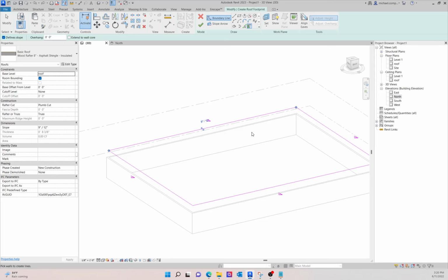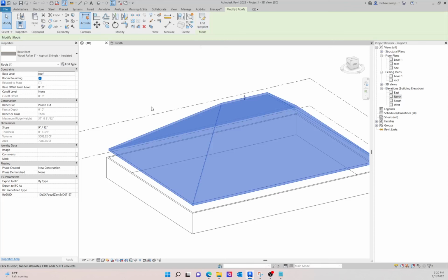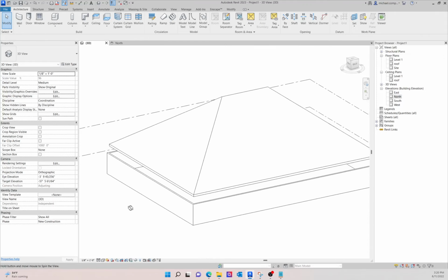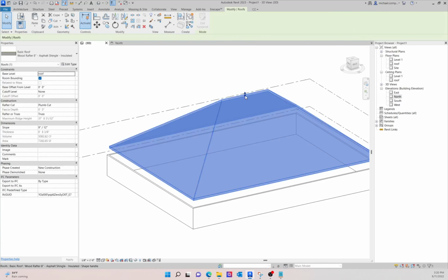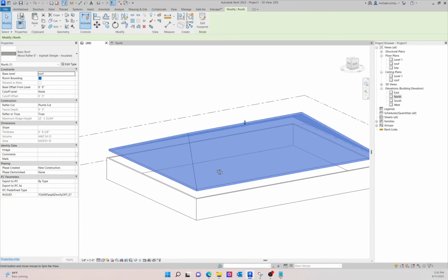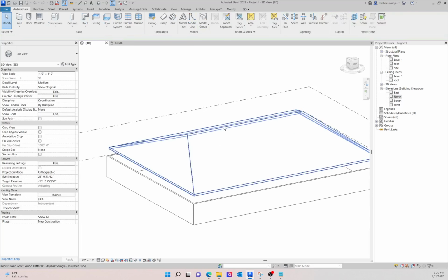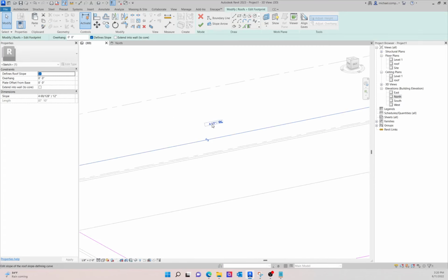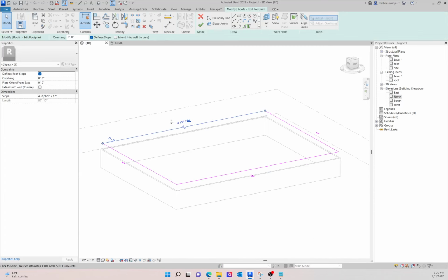So if you're following along, you could probably recognize that this will produce a gabled roof. So a hip roof, excuse me, no gables, a hip roof. So when we hit OK, we have a pretty interesting, pretty high pitch hip roof. And so there's no gables, it's only hip. Now we can also drag down this manually to get something that you're more comfortable with, and that's certainly an option for you. If you hit edit footprint once you've done that, you'll notice that we've gotten to 4.5. So we've cut the roof pitch essentially in half.